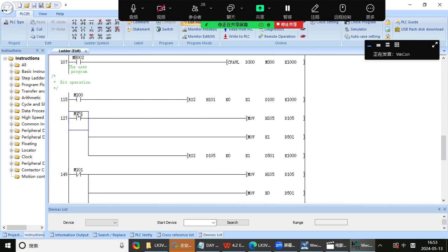when I trigger M101, it will send the data to the PLC. The address is 0, the length is 1, and the value we sent is 1. And we set the communication port from the SNet port on the first BD module, so it's 1000 here.